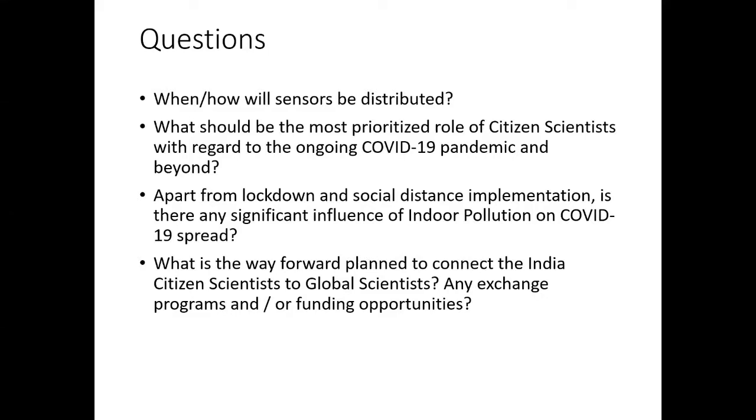It has a long life expectancy, but it does need to be watched, depending on where it's installed, because sometimes plant material or pollen can get stuck in it. There are some cleaning techniques that can be used if you find that the performance has degraded over time. The simplest thing is to put a shop vac or canned air to the bottom of the sensor and try to pull out any dust that's been lodged inside or blow it through.